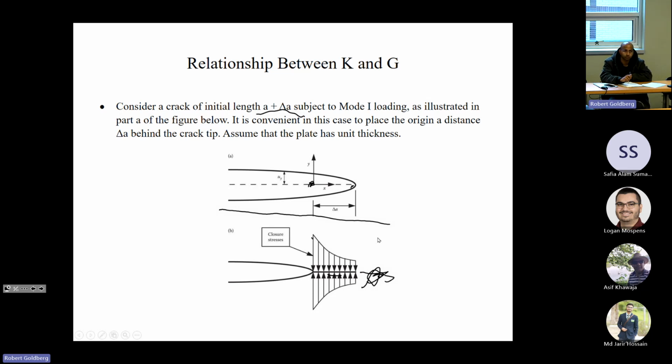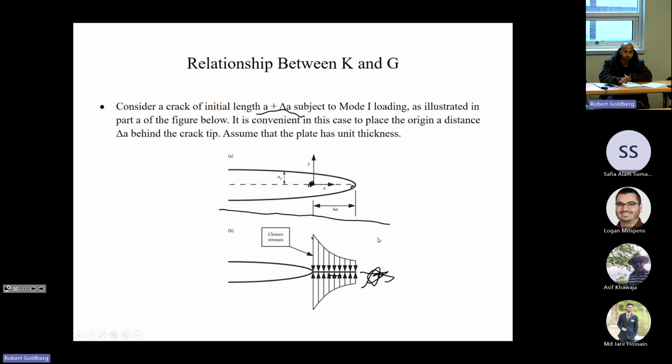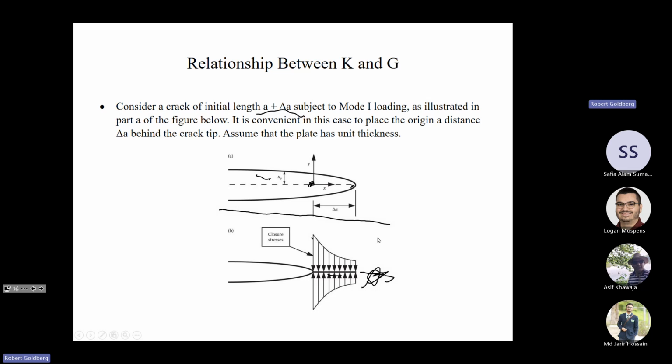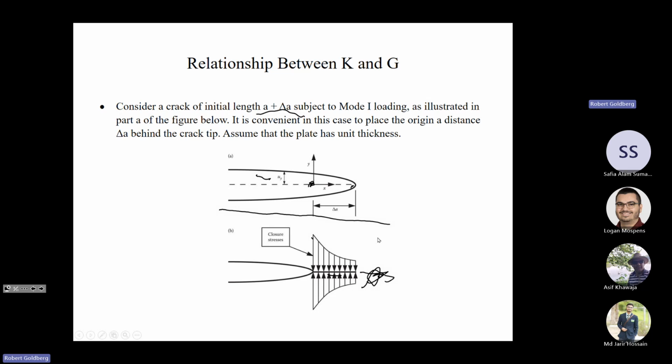And the idea also of this sloped curve is to represent the work required to close the crack. Obviously, right at the edge of the crack, it's going to take less work to close the crack than it is as you get farther in, where you have a bigger displacement, because this uy here represents the displacement from the plane. You're going to need more work to close the crack. So figure that this is a plot of the work required to close this crack from x equals 0 to x equals delta a.